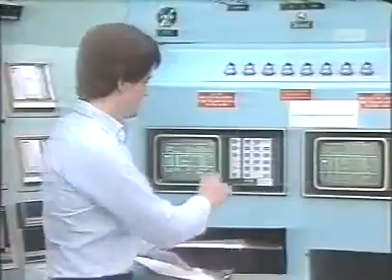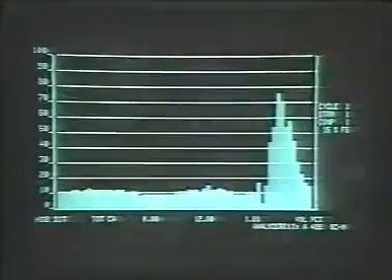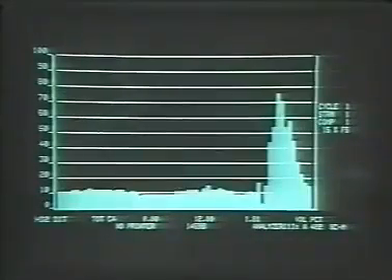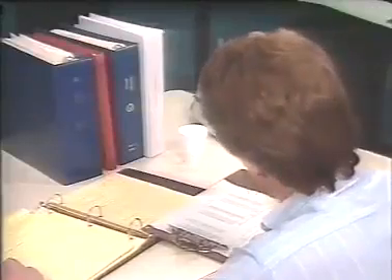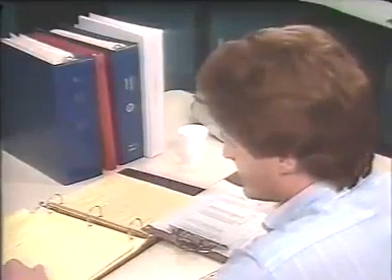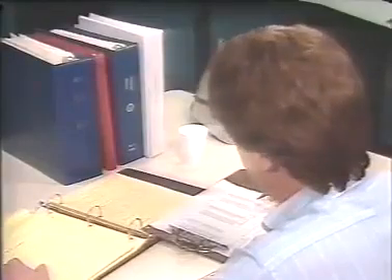On some distillation columns, process analyzers automatically monitor product specifications. These test results and instrument readings are recorded in the unit logbook and are then compared with previously logged instrument readings and test results. If the test results indicate a product is not meeting specifications or an operating variable has changed, it may be necessary to adjust the tower operation. But before making any adjustments, consider the possibility that the tests may be inaccurate, or that an instrument or automatic controller is malfunctioning, or that there is some other mechanical problem.